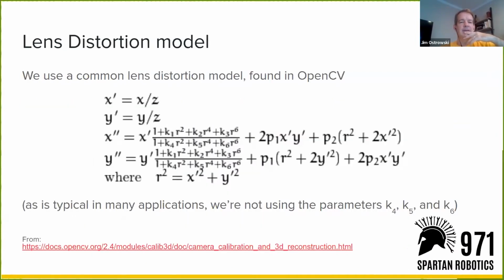Okay. And again, I'm not going to try and dive into this one. It gets a little bit complex, but here are the equations for the lens distortion models. So intrinsic camera calibration also involves estimating these parameters. It looks pretty complex, and it kind of is, but again, the calibration procedures typically will account for these, and you'll get some corrective factors.